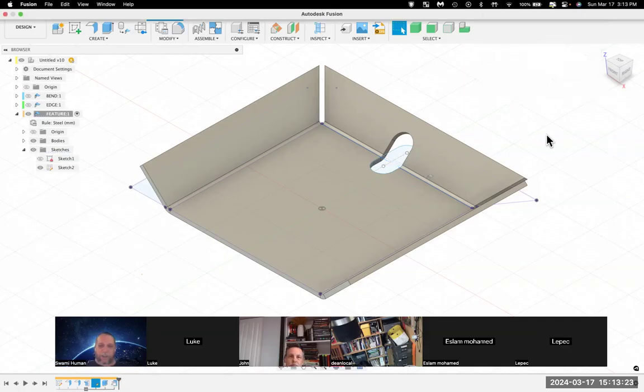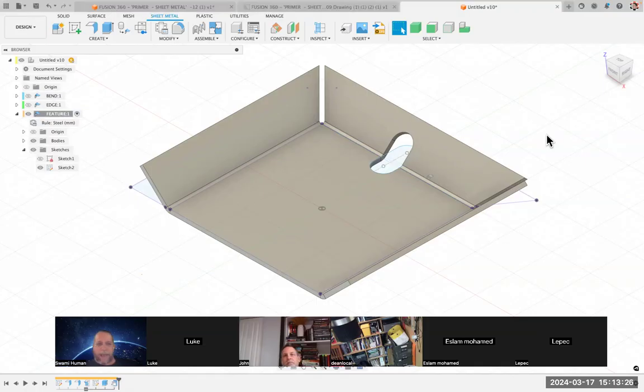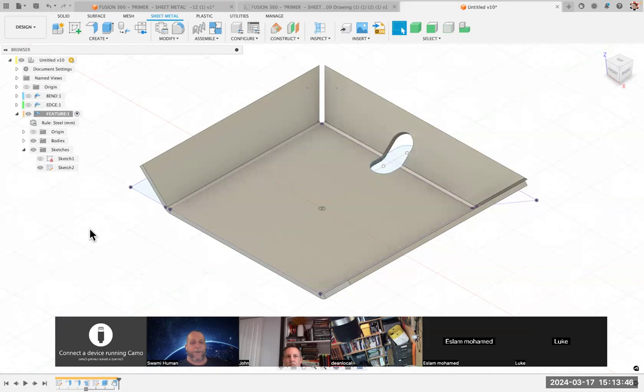Excellent. All right. So I'm going to step back to our previous model because we want to talk about flat pattern. And we're going to compare that to this one. As I noted, the algorithms are different. The purpose is different. And the simpler algorithm to do this, it may succeed and your flat pattern might fail. Now, the ultimate goal is the flat pattern typically, so that you can machine it with your CNC, whatever kind you have. So let's see how the flat pattern works.